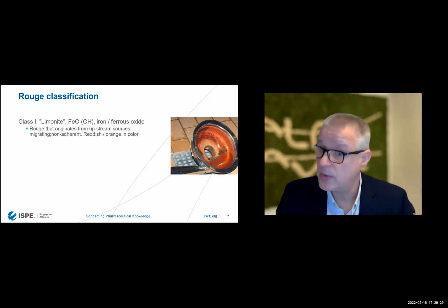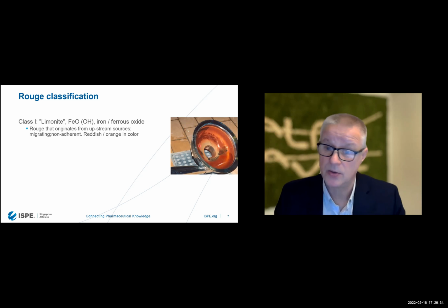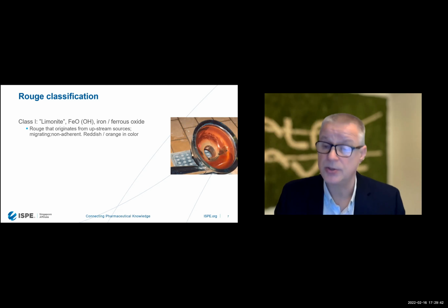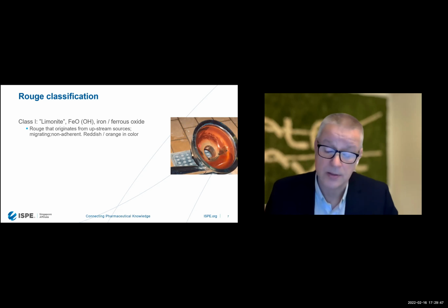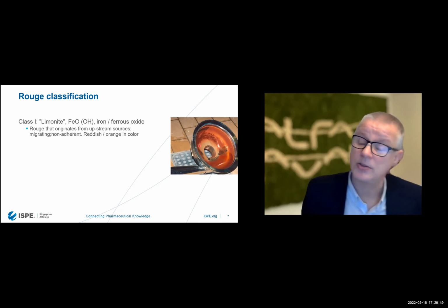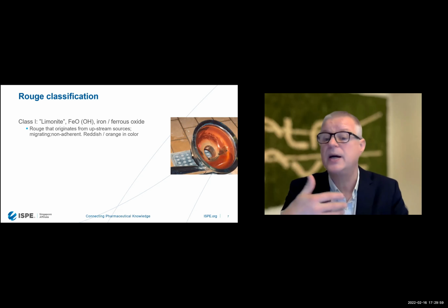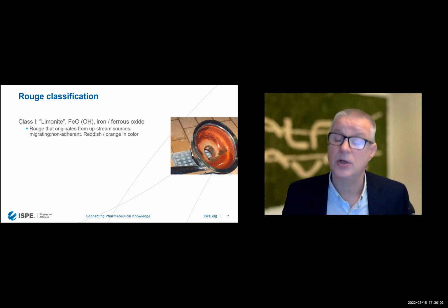Well, it's when you do maintenance, the same thing as you can also check on the PTFE, and then of course you should check the pump, because normally when you do maintenance, you should take the opportunity to change the shaft seal in the pump, because that wears down quite fast, depending on the temperature in the system. But these pumps are operated 24/7 and typically at high temperature, and then you have quite high wear on the shaft seal. So you should open up the pump when you do maintenance.